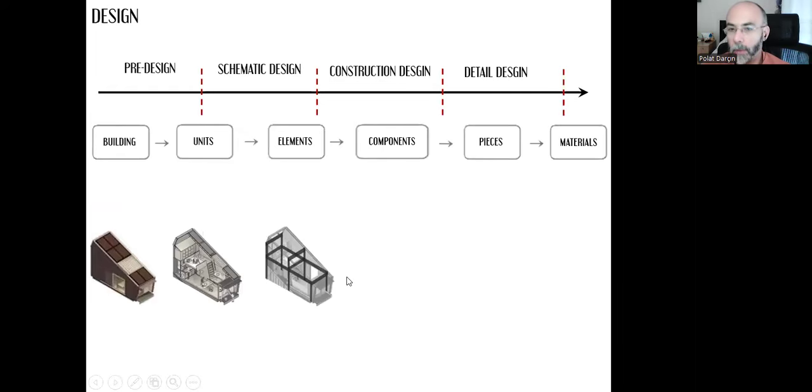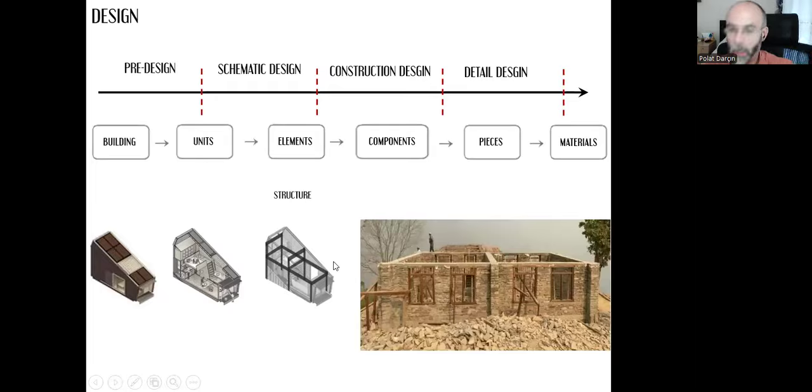If we want to create a stable, a strong building structure, first of all, we need to make the decision about the load transfer, how the loads will be met and carried and transferred. You remember from our last video, this is masonry. All the wall surfaces, all the vertical surfaces, they do the carrying. They meet the loads and they transfer them safely to the ground.